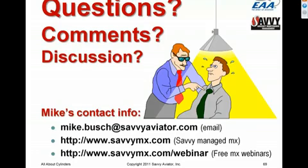Okay, and we had a couple of questions regarding stuck valves and how you can avoid them, or the cause for valve sticking. Could you talk about that a bit? Sure. Stuck valves are mostly a Lycoming problem. We don't see them very often in Continental engines, although we occasionally will see them in some of the older Continental designs, like the O-200 and C90 and stuff like that.